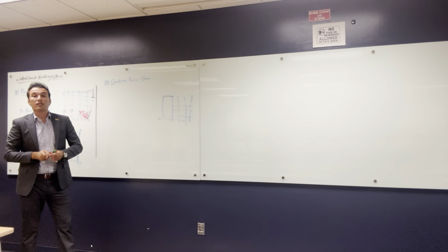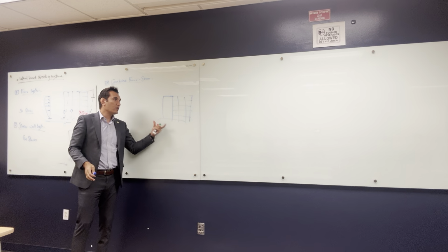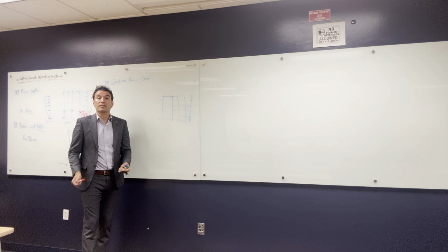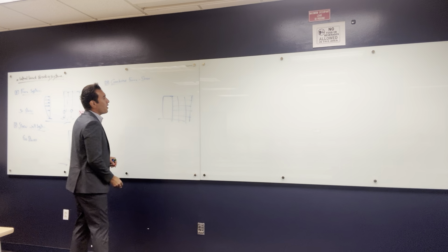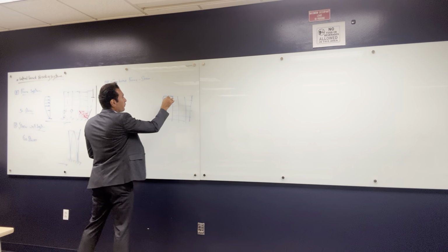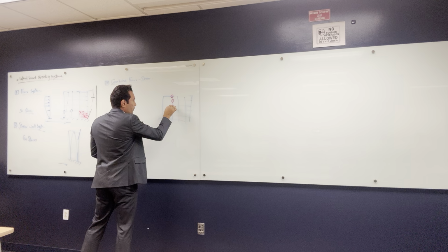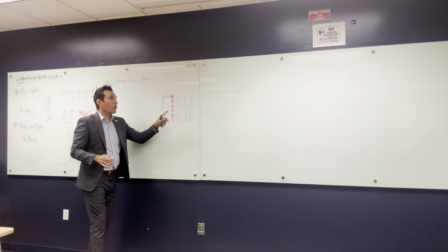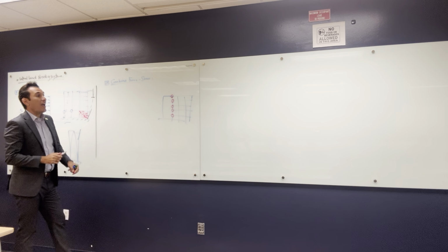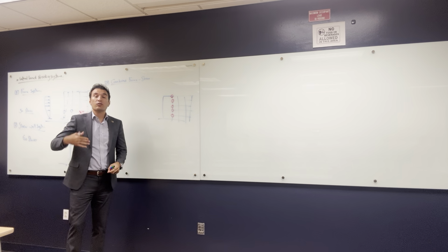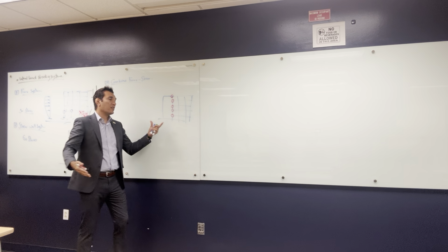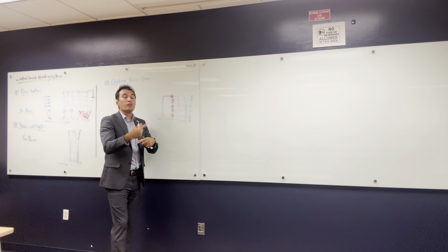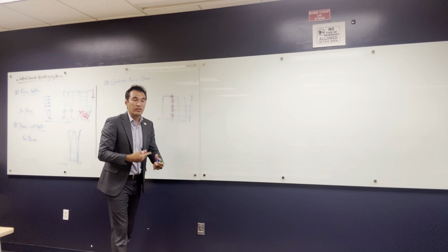And it's usually columns with the shear walls in the building, but usually the shear wall takes a lot of load when the earthquake hits the building, because that's the strongest element in your building. And to enhance the interaction between them, sometimes we enhance this connection so we can make the loads transfer from the shear wall to the frame system. And this can make your system more economical because you didn't let the shear wall take all the lateral force, and you transferred some to the columns, and you made the columns take moment, to take more of the straining actions.